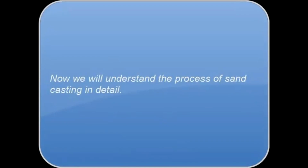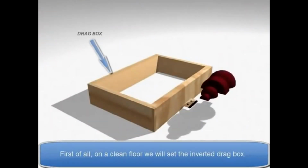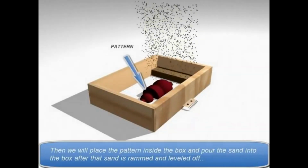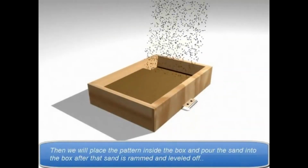Now we will understand the process of sand casting in detail. First of all, on a clean floor, we will set the inverted drag box. Then we will place the pattern inside the box and pour the sand into the box.